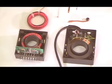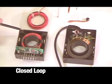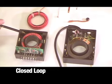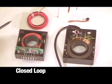Bill, we brought examples of both the closed loop and open loop today. The closed loop is shown here on the left, and what distinguishes it from the open loop is the fact that there's a coil around the core, and that coil has a current that flows in it that exactly compensates or nullifies the current being measured, and when they're in the exact proportion, that's when there's zero flux in the core.